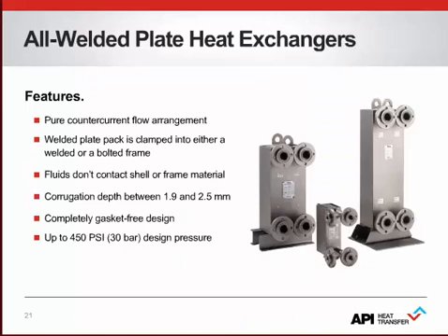Again, we have the pure countercurrent flow, like in the gasketed plate heat exchanger. The plate pack is installed in the same way into a bolted frame. The difference is that the gaskets are replaced by welds. This includes also the gasket to the connection flange. So the complete heat exchanger is welded and does not contain any gasket at all.